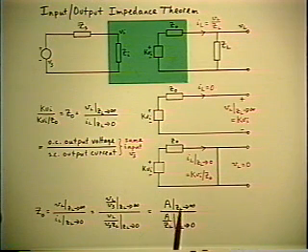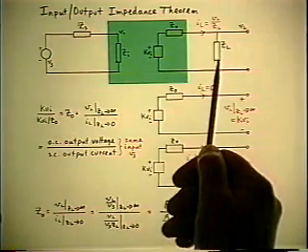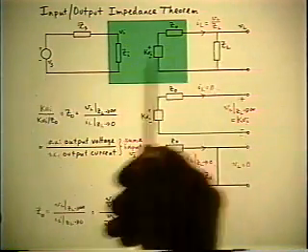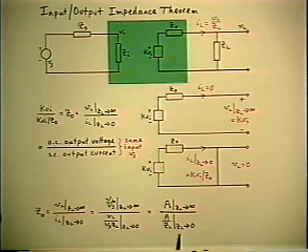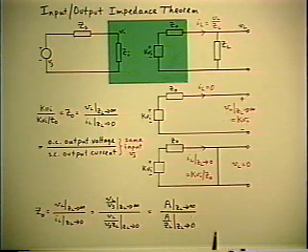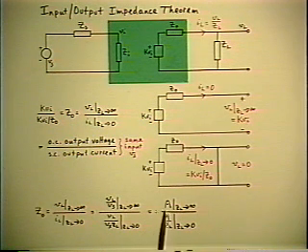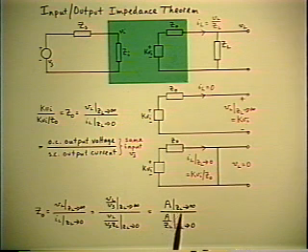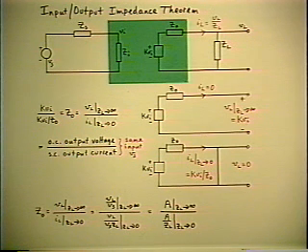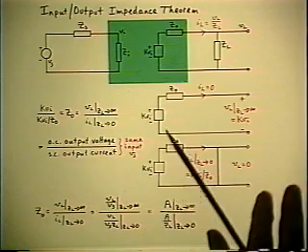And you can do that because the ZL is inside the A, because it's there when you calculate the A. So taking the two simple limits represents the only additional amount of work you have to do to find the output impedance over and above the work you've done already to find the A. And even without trying it, it's pretty easy to see that there's not much involved in doing that. So that's the output impedance theorem.